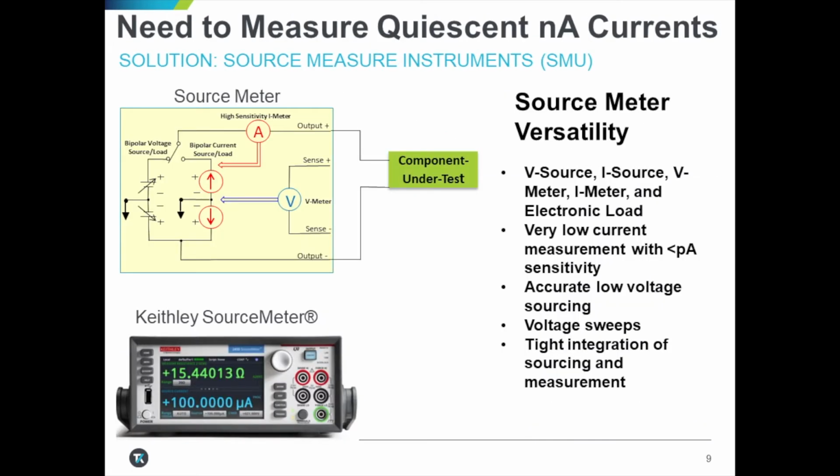In order to properly select low power components, one has to frame the following design questions. What is the current draw at operating voltage? How much does current draw change over battery voltage decreasing? Is there a problem in evaluating any portion of the power consumption across the range of your components? And are you evaluating low power components with ultra deep sleep mode in mind?